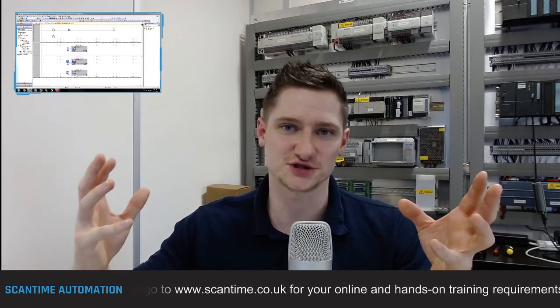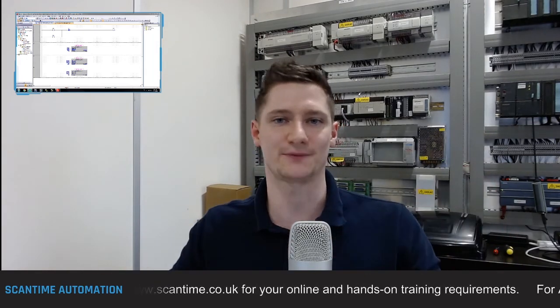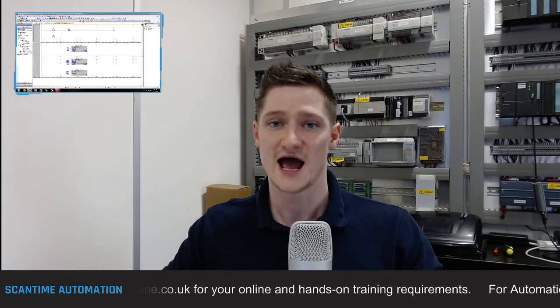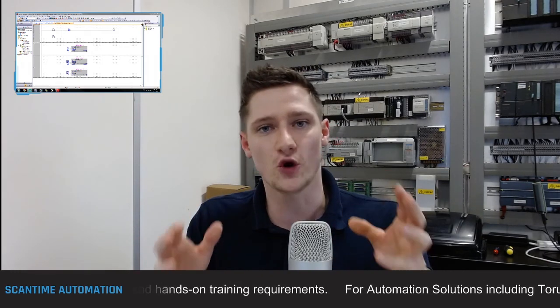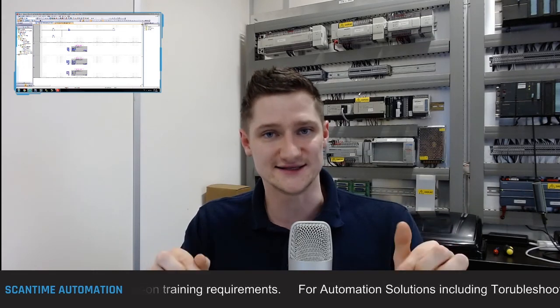As I mentioned, it is just a very basic program. I didn't want to go too in depth with having several networks designed inside of there. I just wanted to show you quickly how we can design function blocks inside of GX Works 2 and then use them inside of the main program. Because if you're working on the shop floor now in today's industry and you open up a ladder program like this, I would be very shocked to find out if there are no function blocks being used. And that's all I wanted this video to be, just a brief introduction to function blocks within GX Works 2, how to create them, how to assign local tags, how to assign a data block to them inside of the main program, and then how to monitor them inside of that program.